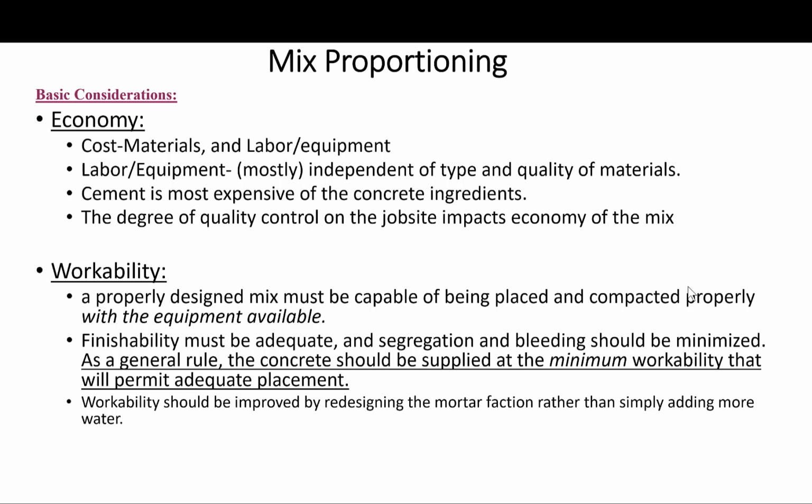So there are certain considerations that you need to consider when designing a mix. The cost of the concrete is basically made up of the costs of materials, labor, and equipment. However, except for some special concretes, the costs of the labor and equipment are largely independent of the type and quality of the concrete produced.